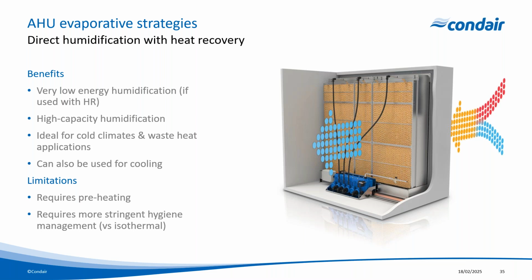The other limitation here, when we start moving into cold water, adiabatic, or evaporative systems for humidification, is of course the hygiene consideration. Limitations on the hygiene side are typically a bit more stringent compared to an isothermal system where we're boiling the water, really killing anything that's in that water being used for humidification. Whereas with an evaporative system, you may have potential concerns over bacteria and hygiene of that water quality because we're not boiling that water.